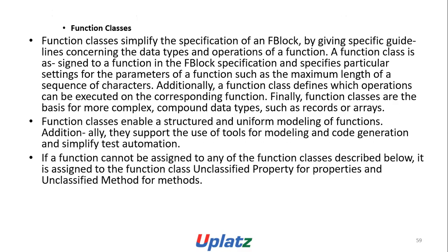Function classes simplify the specification of an FBlock by giving specific guidelines concerning the data types and the operation of a function. A function class is assigned to a function in an FBlock specification and specifies particular settings for the parameters of a function, such as the maximum length of a sequence of characters. Additionally, a function class defines which operations can be executed on the corresponding function. Finally, function classes are the basis for complex compound data types such as records or arrays. Function classes enable a structured and uniform modeling of functions. Additionally, they support the use of tools for modeling and code generation and simplify test automation.